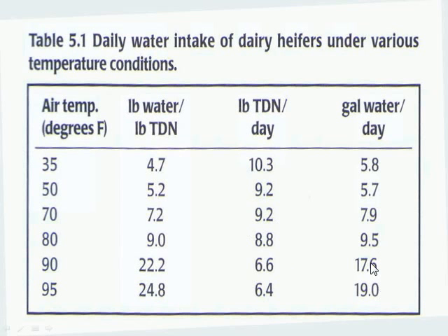So there we're back to that heat index thing. If we got a lot of days where the amount they're needing is that high rate, then we're going to have to design for that. Whereas if you're going to have very few of those days, then you wouldn't have to have as many gallons of water per day per head.